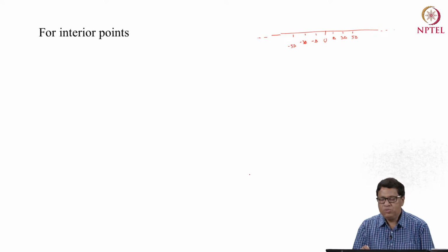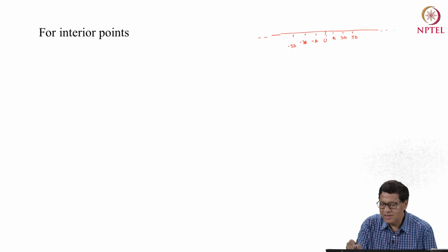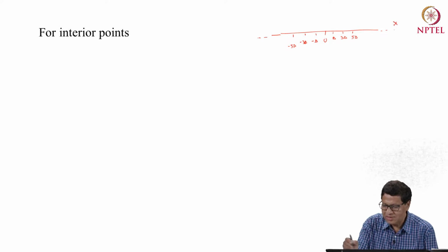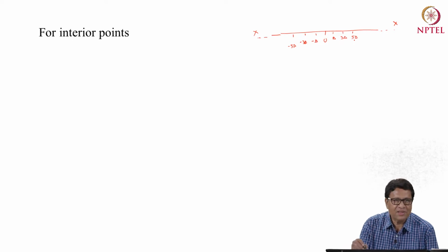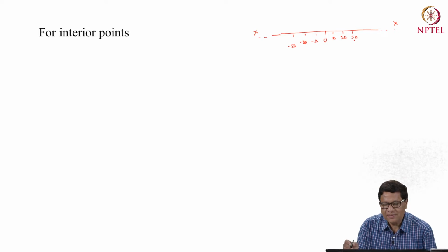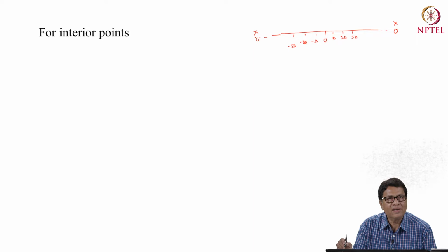So there are two types of constellation points here. One is the points which are inside, that is, you exclude the point in the last at either end. The other points are the same. So if the noise affects any constellation point, plus minus delta this way or that way, there will be an error. It is different for endpoints. So we will separately handle the endpoints.